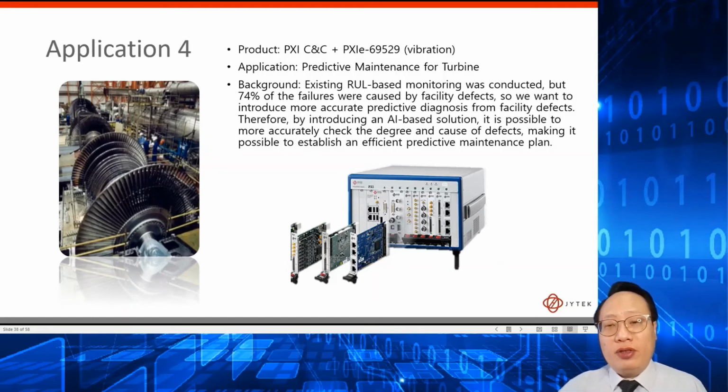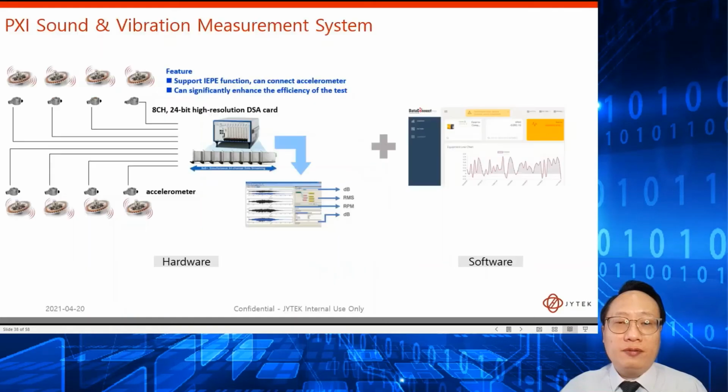One of the results of the prediction is a RUL, or remaining useful life parameter, where it will predict not only failures of the engine itself, but up to days or sometimes hours before the failure happens. Once the prediction is done, the technician can go in, remove the engine from operation, and perform diagnostics on the engine itself.